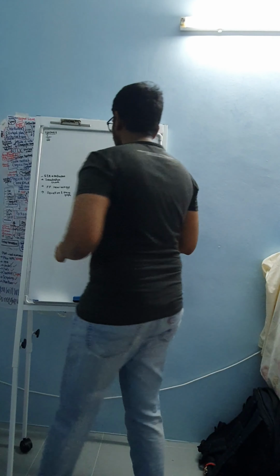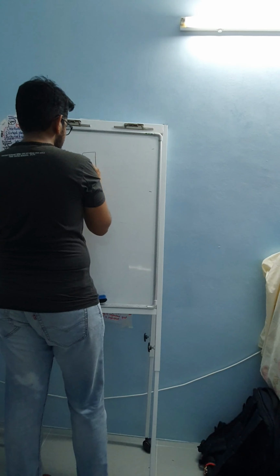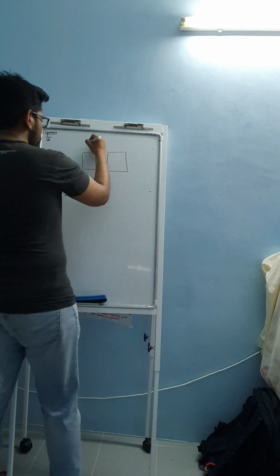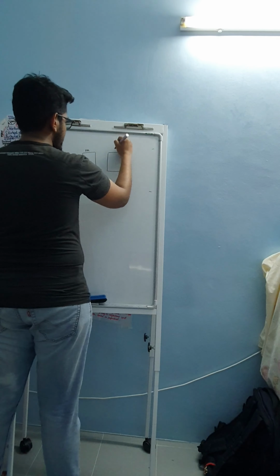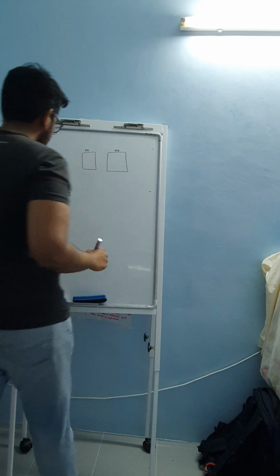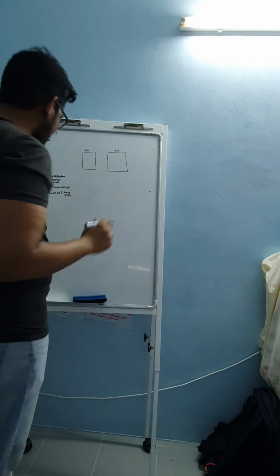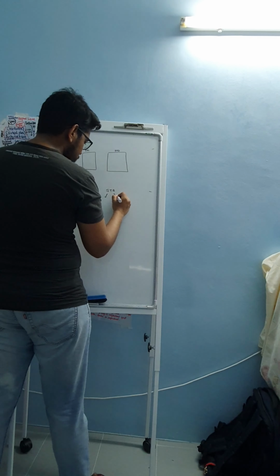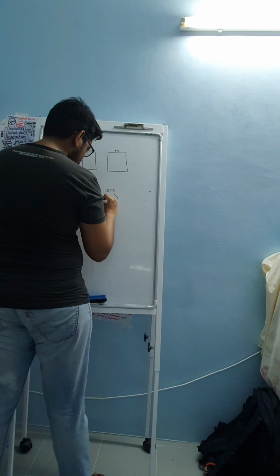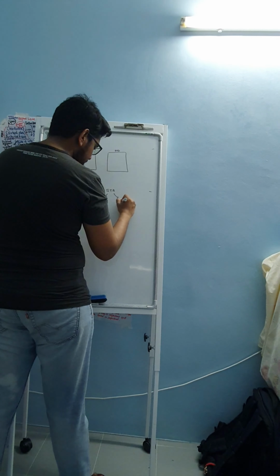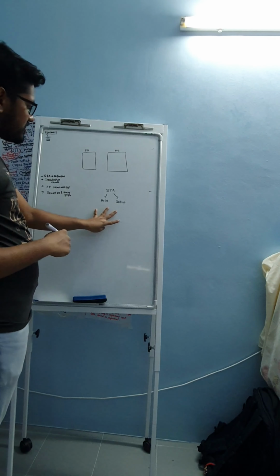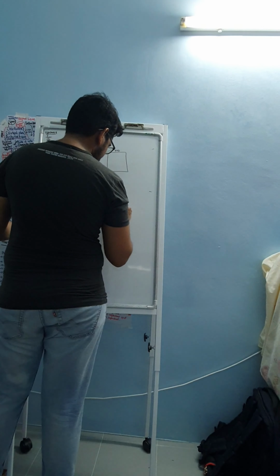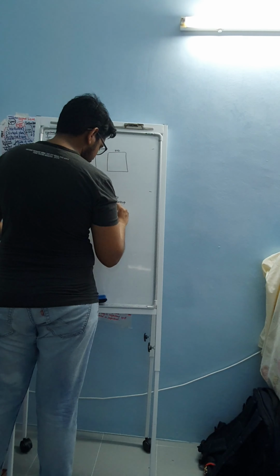So let's draw a flop over here. This would be your FF1 and this would be FF2. Before I move on into this, let me explain to you that STA comes in two parts, hold and setup, which are very important. Everyone should really understand how these two timing checks work. So this is considered a timing check.